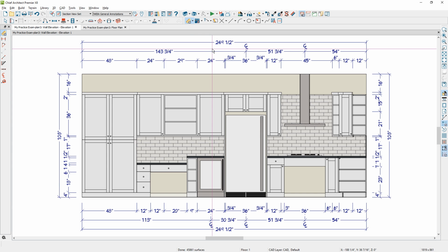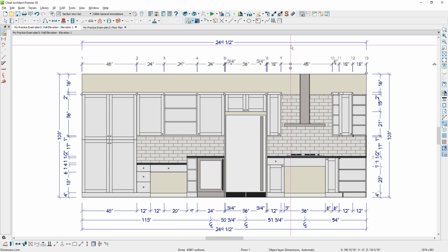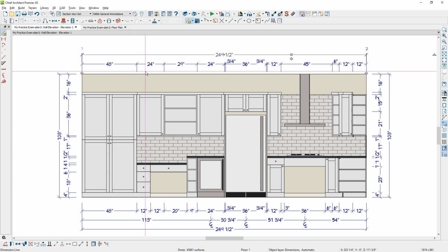Let's go ahead and begin the cleanup on it. We'll start at the top. So I'm going to go ahead and delete the center line. We're going to assume that the cook hood, you could have the center line for the cook hood, but it's also going to be from the cook range at the bottom. So I'm just going to delete that. And you'll want to verify that that's an accurate thing to do for your plans. I'm just going to kind of speed through this a little bit. Pull this dimension down, 48, 24, 29 as we kind of go through here.